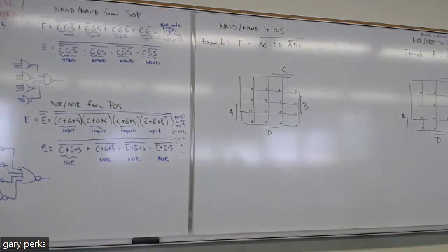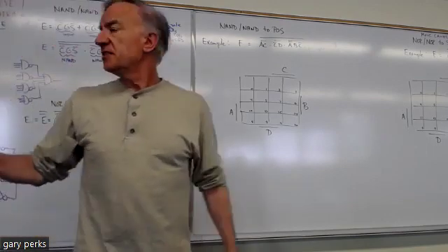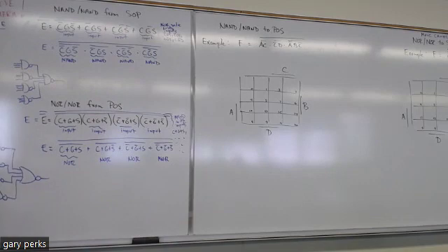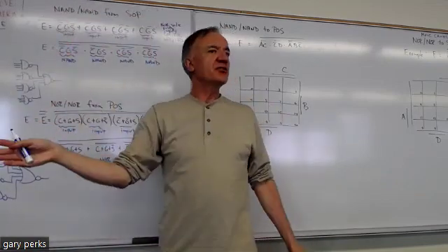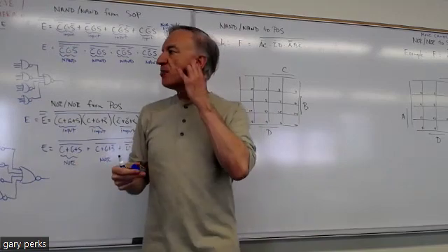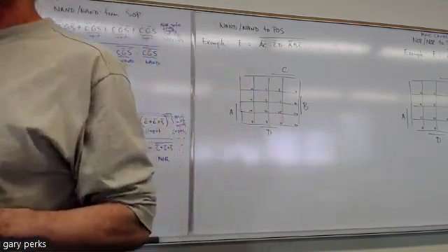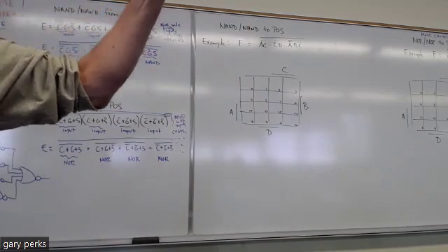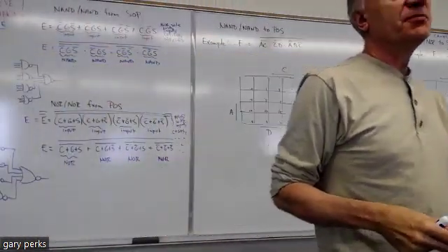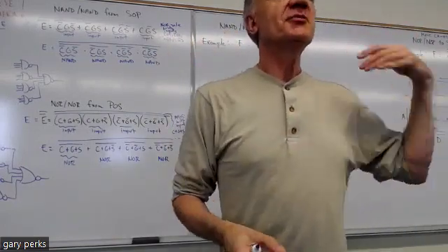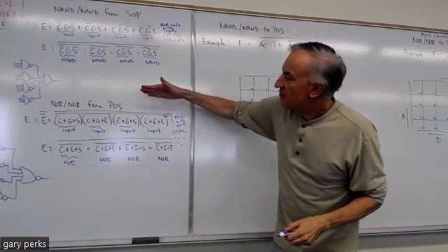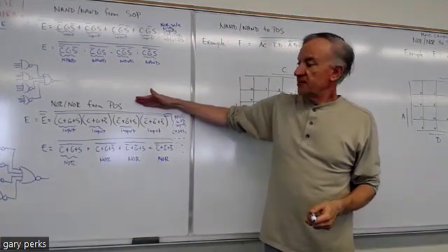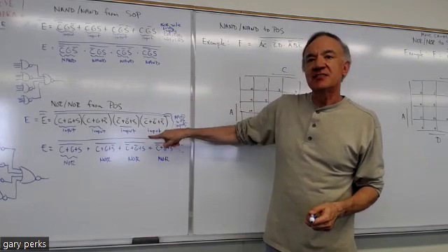Okay. And all these different forms here, as long as they come from the same truth table, SOP, POS, NOR, NAND, they're all logically equivalent. So in your lab one, as I said towards the beginning, based on last lecture, you could come up with reduced SOP, reduced POS. Based on this lecture, you'll be able to come up with the reduced NOR. Because once you have the reduced POS, to get the reduced NOR, you just do this.